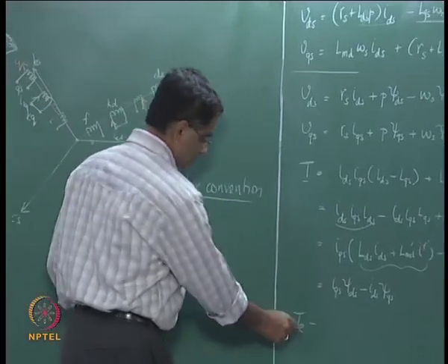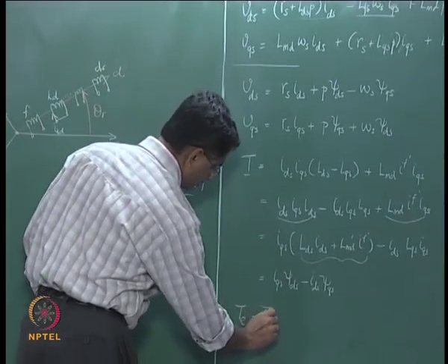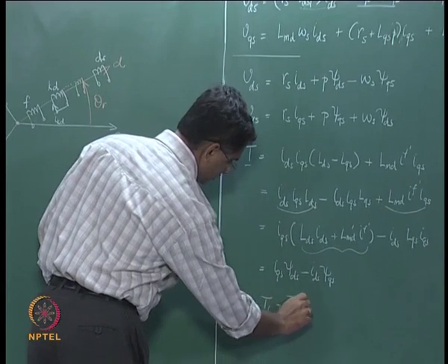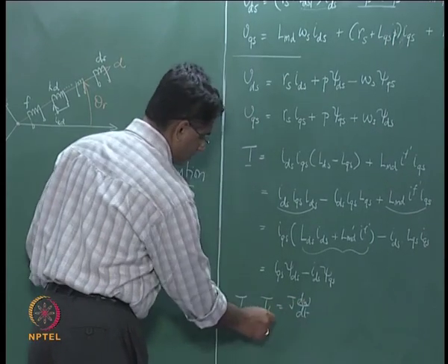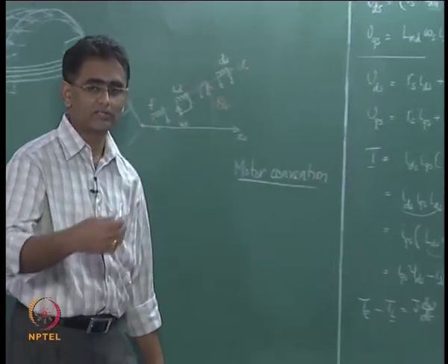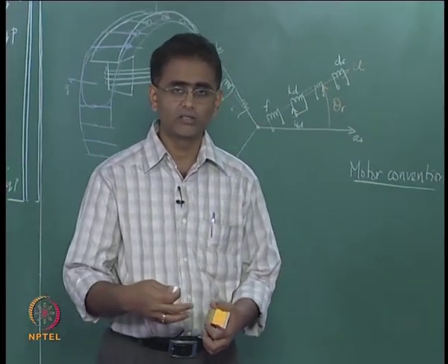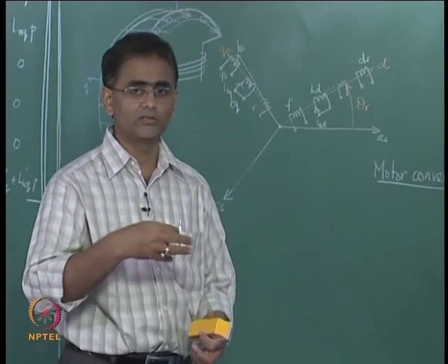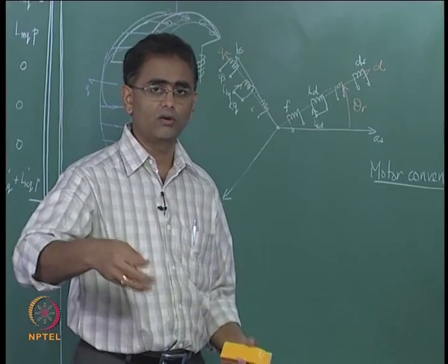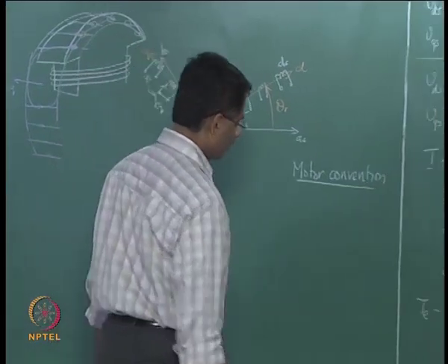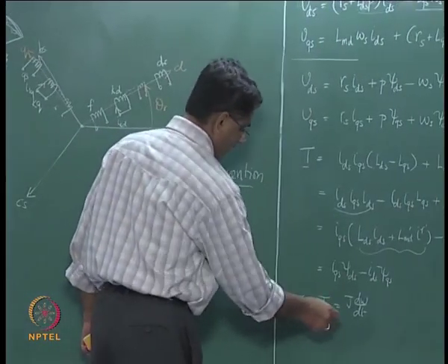And therefore, using this convention, the generated TE is output from the machine, it is a mechanical output. So this mechanical output minus the load torque is going to result in an increase in speed. Load torque may then consist of a fixed component and in addition viscous friction drag components, which are to the exponent of omega 1, omega power 1 or omega squared and so on. So all those terms are going to come into TL.